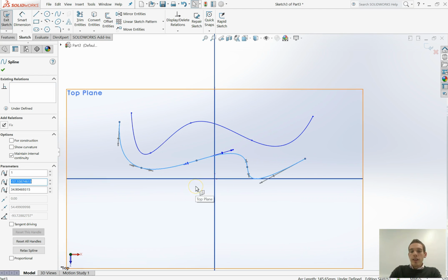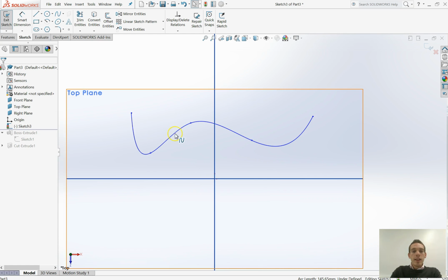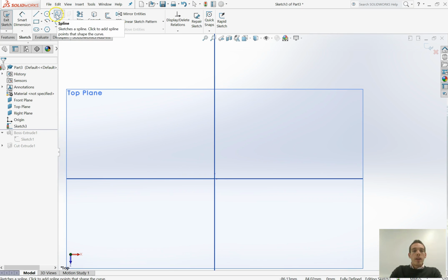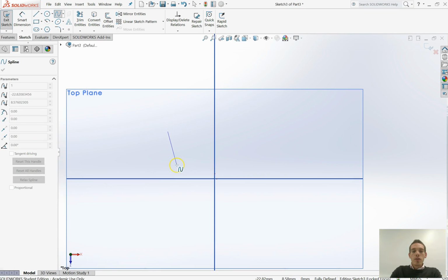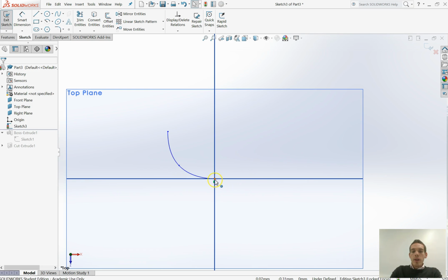Right, what I'm going to do is delete that. So I've selected it, I just hit the delete key on my keyboard, and select this one and hit the delete key as well. Okay, so if I want to draw this teacup, I'm going to go for my spline initially. I'm going to draw one point here, point here. I'm going to snap to the middle bit because that's where I want the middle bit to be. Now I've got a few different options here. I could just draw the other side, or I could exit my sketch. So exit that last point, that middle bit.